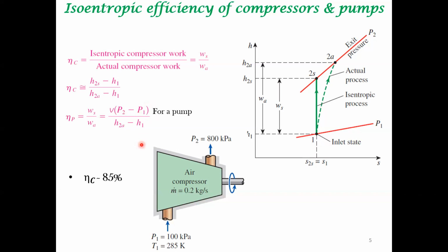So the typical efficiency of a compressor is about 95%, which is also high. As you can see, even though each of these components acts at reasonably high efficiency, the entire power plant doesn't operate at this efficiency. It's about 40 to 50% efficiency.